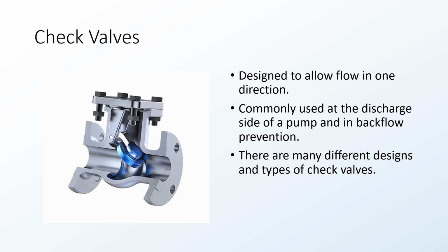Check valves, super important. There's typically two of them on your backflow device, right? For anyone who's taking backflow. But you can install these, or customers can if they want, to prevent water from traveling back out into the distribution system. If a customer has a pump that they need to increase their pressure because you're only providing them the minimum requirement, they might install one of these to prevent their system from losing all that pressure.